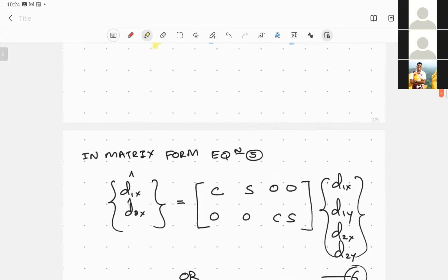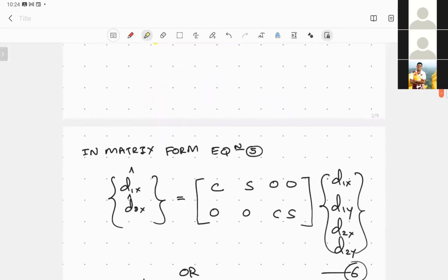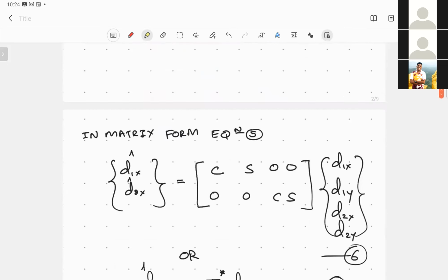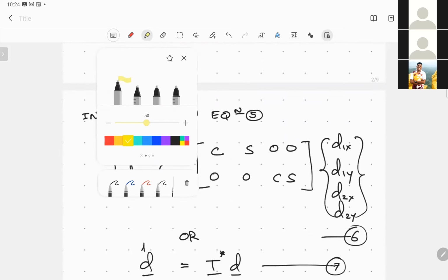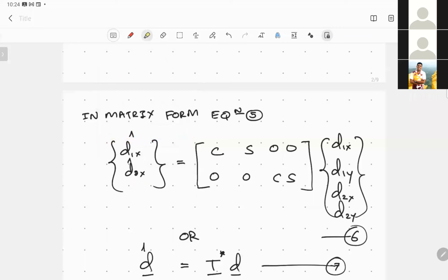What I'm trying to show is how we can expand the matrix so that we come to the rank of the global stiffness matrix. So we are interested in displacements in the x direction as well as y direction in the local coordinate system, which can be expressed via the nodal displacements in the global coordinate system using this relationship.